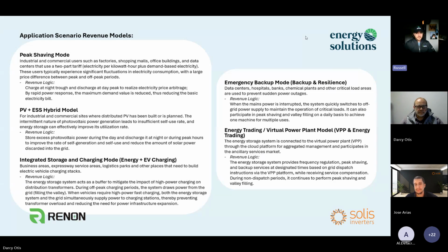It'll do a slow and continuous draw of energy, never driving up your total peak. You can actually have it tied into CTs that monitor what the total peak has been thus far this billing cycle, and then make sure to only ever charge the batteries when you are below a particular threshold of safety away from your current peak within that cycle. So a lot of really cool advantages that you can create from this approach.